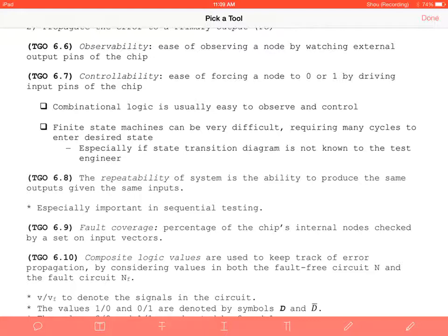So if it's intermittent, it's maybe because you haven't properly accounted for noise margins. So sequential circuits are very important in being able to hold a value through feedback. So if you haven't accounted for your noise margin properly, you might have loops and then it starts at 1 and then eventually kind of trails off to 0. So that's kind of an intermittent fault. But if you put it in again, you should be able to get that same error using the same set of conditions. So your test vector has to account for this.